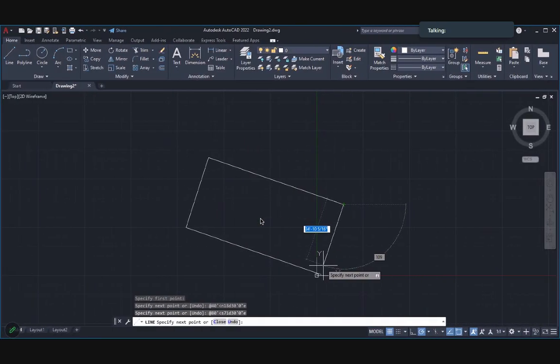Okay, so in AutoCAD I'm going to put in my length first, 40, and then apostrophe, and then the angle sign. Okay, one backspace, and then S for the south, and then 18, letter D for degrees, and then put in 30 minutes, and then 0 seconds. That's quotation, and then W for west, and then press enter.